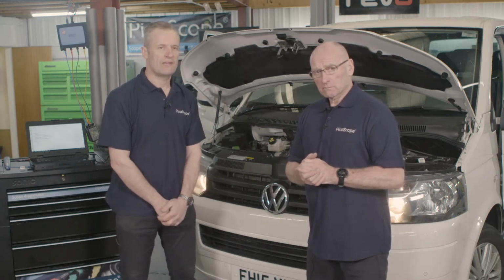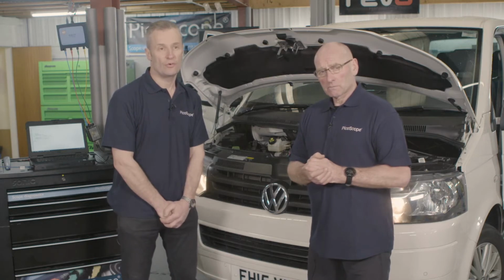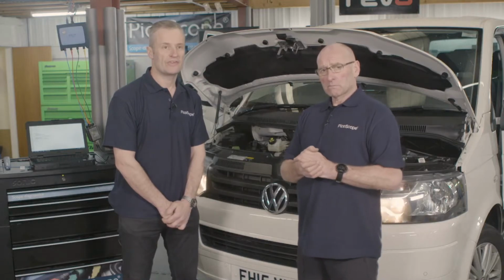Yeah, the opportunities are endless really, because certainly always keep a microphone in the cabin as a reference, because that's what the customer can hear. Perhaps keep one in the cabin, one in the engine bay, and also keep the accelerometer as well, so you've got 3 points of reference really. Think of bearing noise if you've got the luxury of 4 microphones, 4 accelerometers, 1 road test, 1 measurement with a reference inside the cabin.